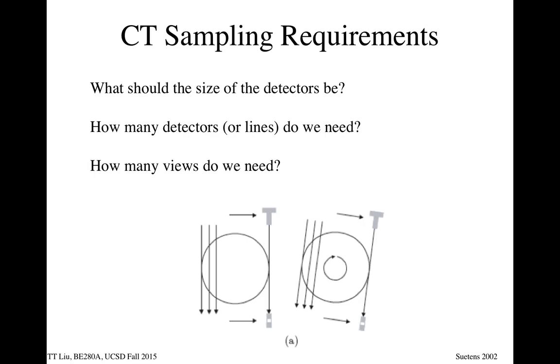The question came up a couple of times. It's a natural thing to ask: what is the requirement for sampling, since we've discussed the adequacy of sampling at a specific rate to avoid aliasing? Therefore in a CT scanner, what rate do you need to sample, both along a projection and how many angles would you need to make a picture that has adequate resolution and lack of aliasing artifact.